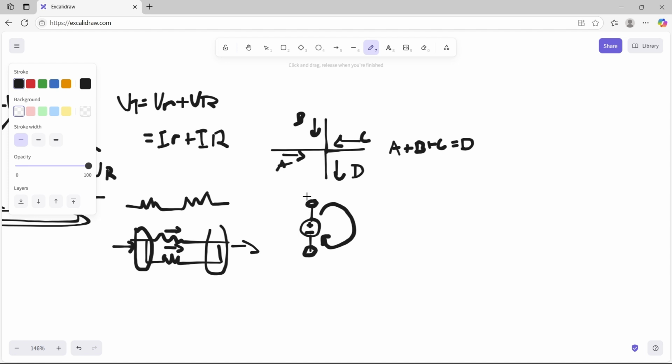And something that we'll see in much more complicated circuits, that would become relevant when we get to dependent sources or even current sources, is that the voltage source will generate as much current as it has to in order to fulfill this condition, that you always have a stated voltage across those two terminals.